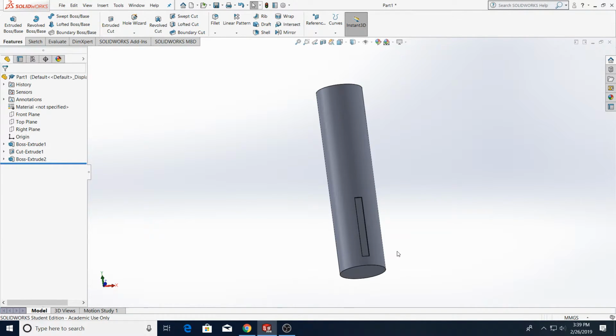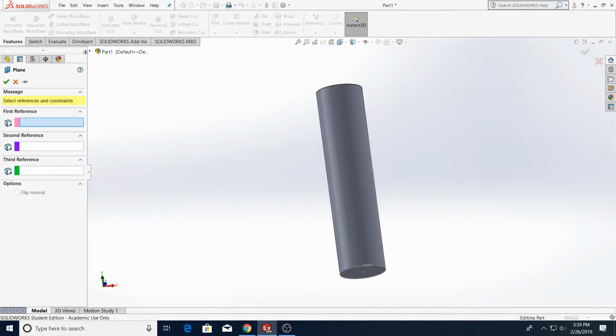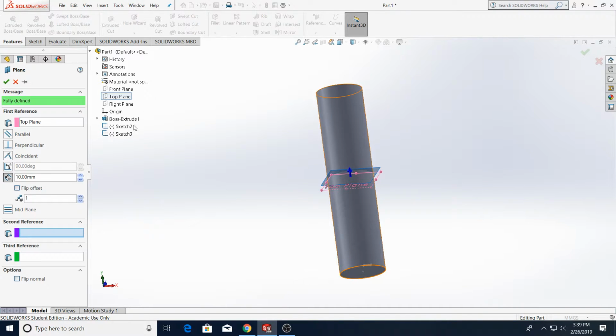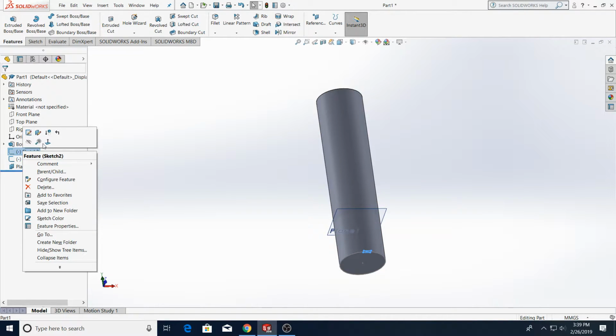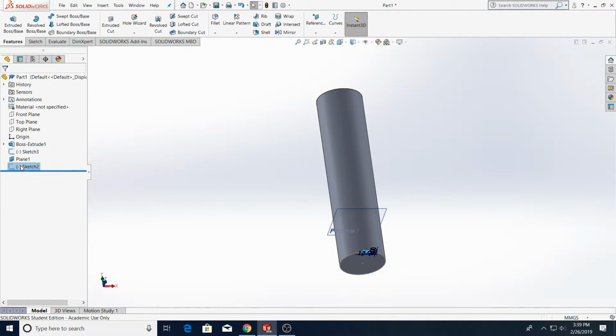In my opinion, the more elegant solution would be to create a reference plane. Either you create a reference plane on a top parallel plane, so you could do something like, let's go with a reference plane relative to the top or bottom, and we say it's offset maybe 100 millimeters like this, wherever that actual cutout was located. You'd have to align it with either the top or the bottom. And now we could create a sketch on that plane. That was our rectangular cutout. In this case, I already have that drawn, so I could just move this sketch plane to plane 1 like this.